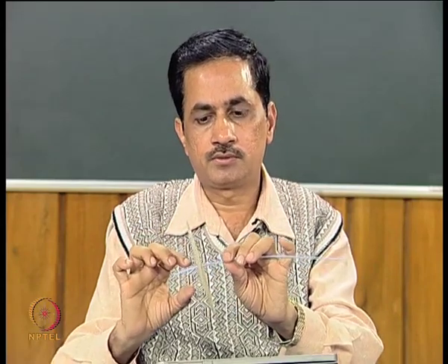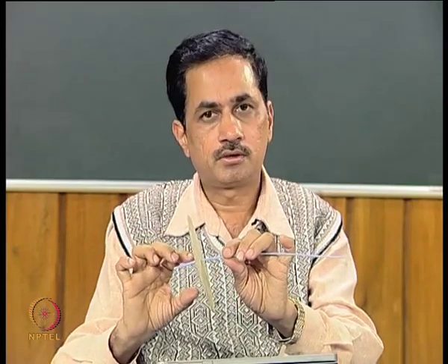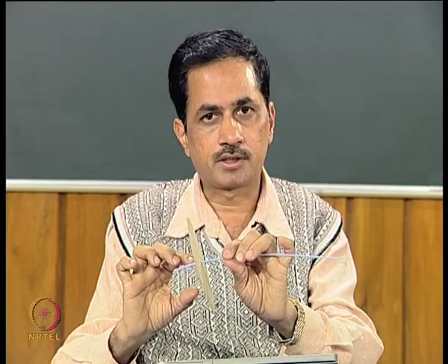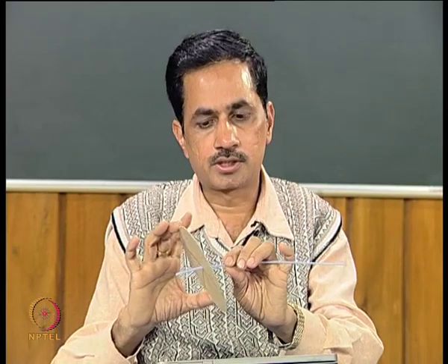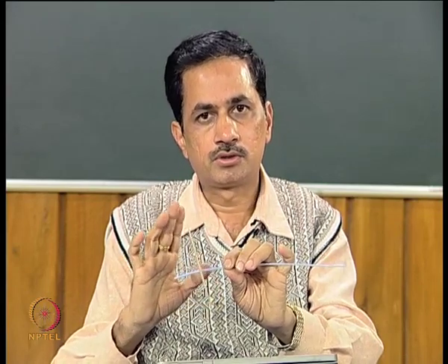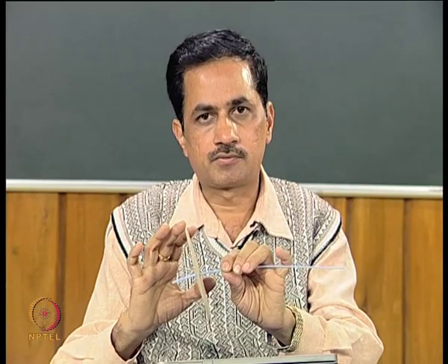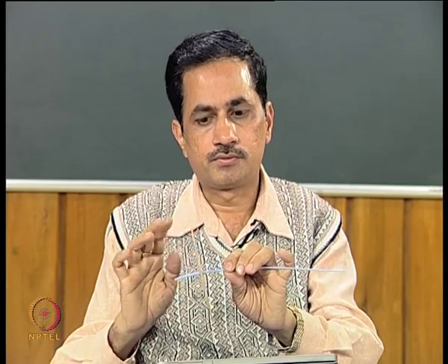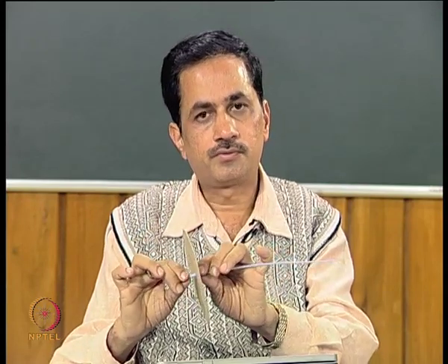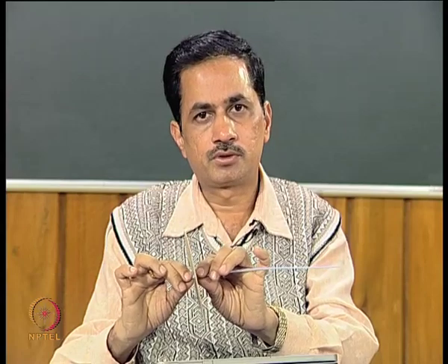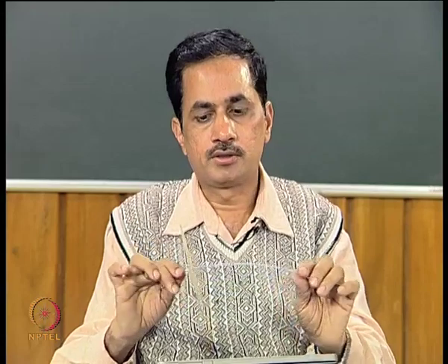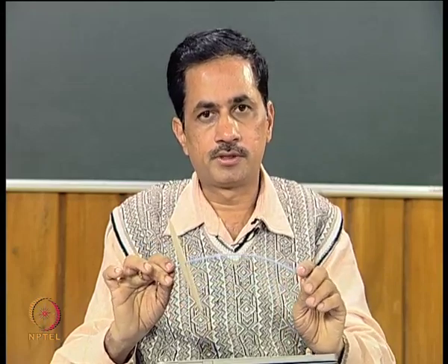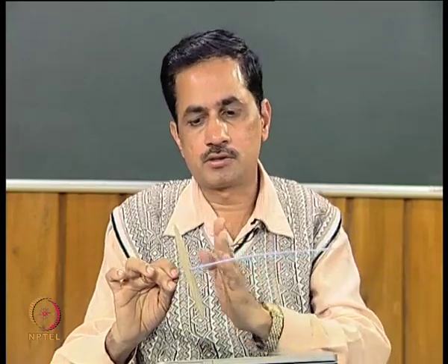So not only do we need to define the two translational displacements x and y, we also need to define the tilting of the disc about two axes, that is x and y axis. So here we will have 4 degrees of freedom or 4 variables to define the position of the disc, and this is the variant of the Jeffcott rotor, in which the disc is offset from the center.